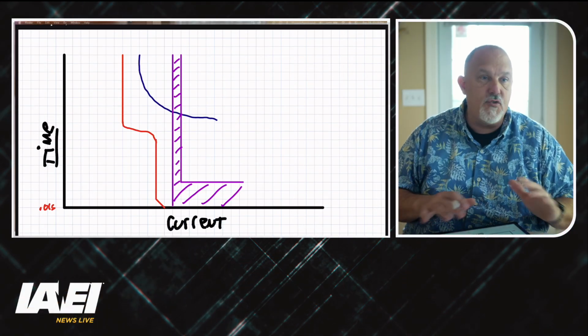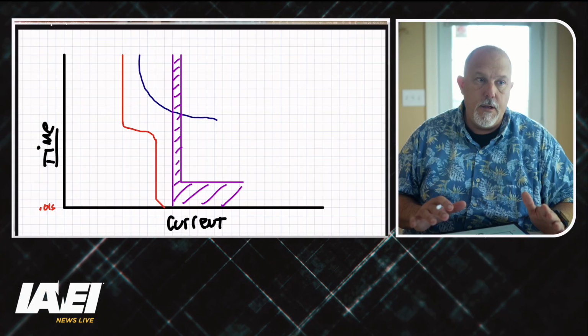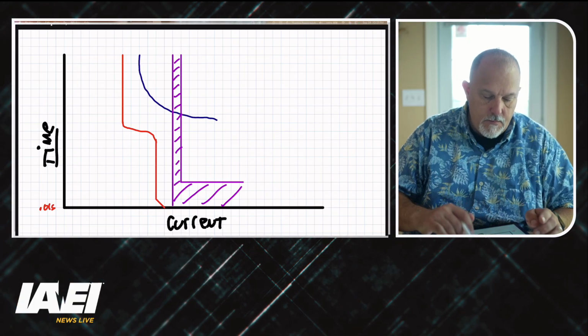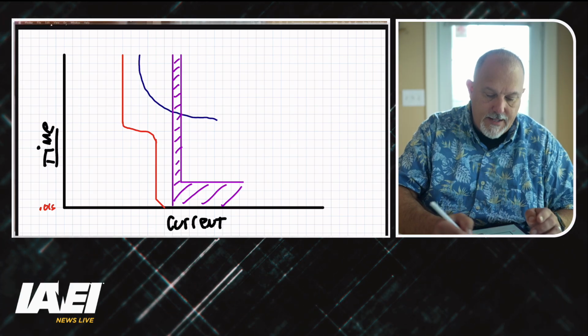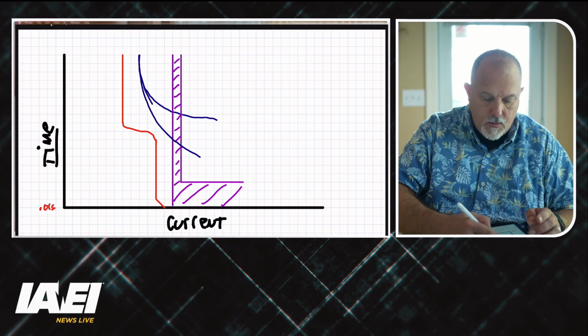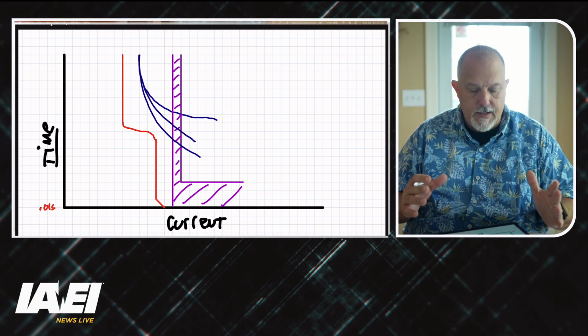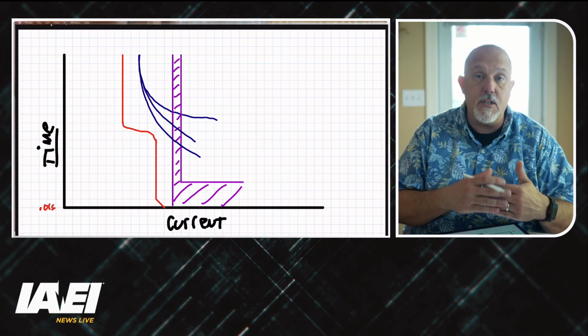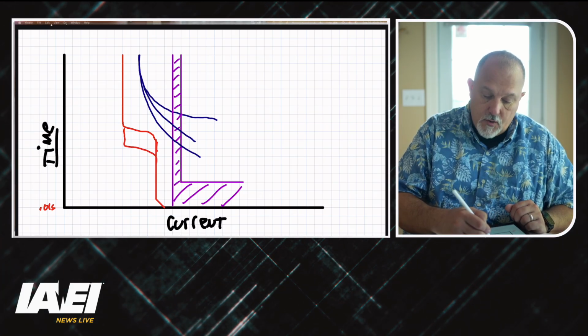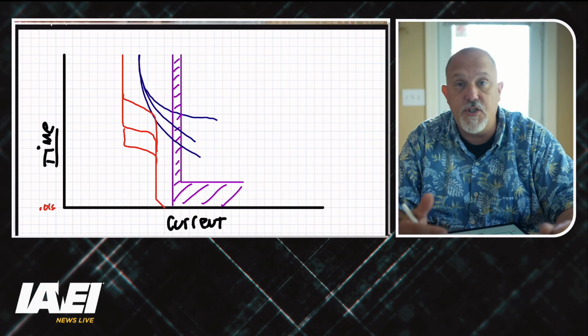So when you follow those rules, selecting those overcurrent protective devices first, narrowing in and solidifying the application with regard to these types of trip curves, and providing protection for the motor, letting the motor start, whether you have this type of curve, whether you have that type of curve or that type of curve or this type of curve, the slope of that curve to accommodate the starting of that motor, whether your knee for this motor is there, or maybe it transitions earlier, or maybe it transitions later, depending upon the load that it's driving.